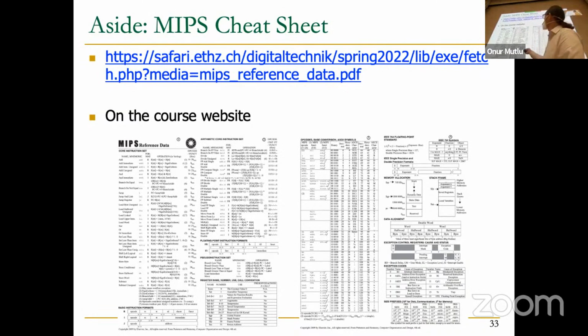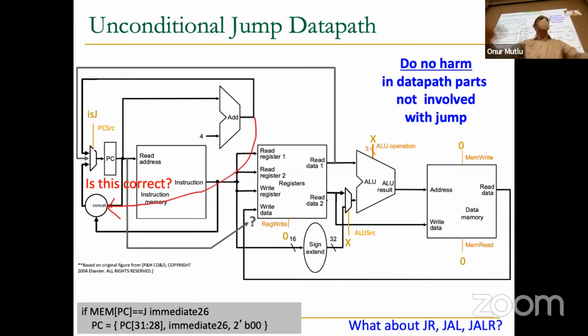There's also floating point instructions that, well, they're also here, but basically you need to support every single instruction, which means that your data path will become bigger and bigger, and your control signals will become more and more. But the process that I've just described is essentially the same. You add data path elements to support the instruction, whatever data path elements they may be, and then you add control signals to support the instruction, and you make sure everything works. Sounds easy, but with a complex instruction set, it gets bigger and bigger.